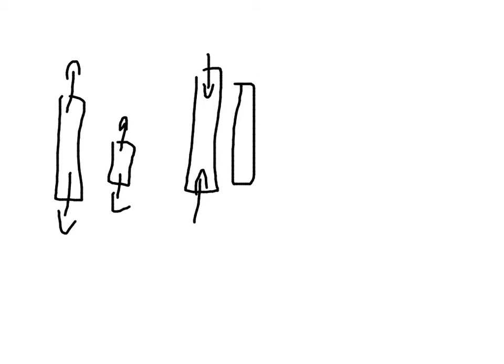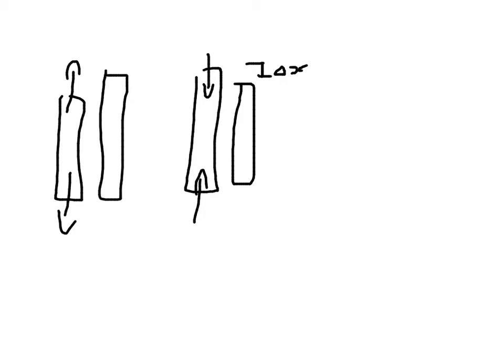We've also got other forces which have other moduli associated with them. We've got compressive forces, i.e. where it's in compression. And here your delta L, or delta X, whatever you wish to call it, is not an extension but a change in length that way. That's the only difference between the equations. We draw like for like: rather than an extension as your delta X, you're now talking about a compression as your delta X.